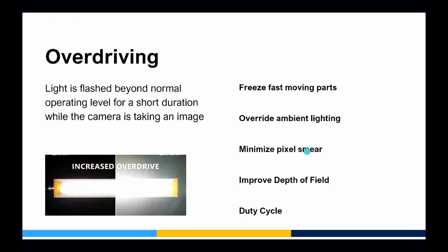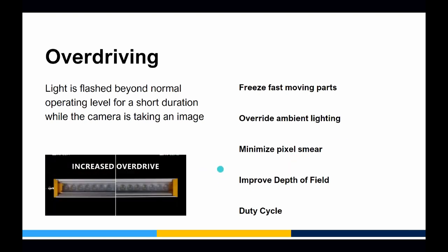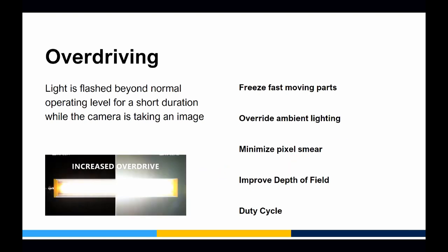We're allowing rest in between each flash. So the downside of overdriving is that you're putting more current onto an LED, so it has to have time to cool down so it doesn't get overstressed. So this is where we have to factor in and consider our duty cycle. So the duty cycle is the overdriving time plus rest time.